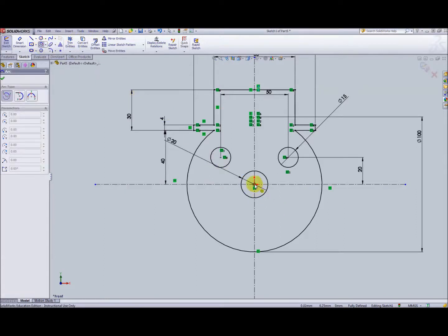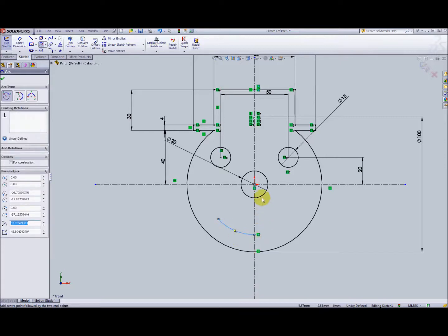Now this time we're going to start on the origin in much the same way as we used to create the circles. We're going to drag a line out, and as you can see, it's starting to look like a circle, and that defines our diameter. And then we just drag, and we define the width of the arc. We're going to stop that, snapping it to that vertical line like this, and that's the first of our center point arcs.